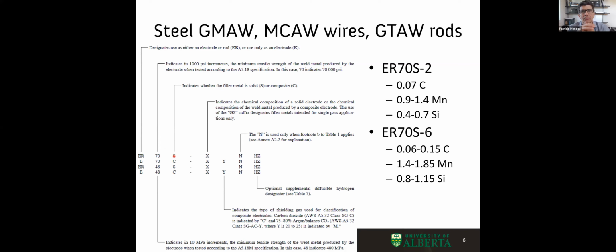Now, if we are doing metal core, because it's a metallic sheath, a tube with a powder inside, that is called a composite. And there are other types of wire that are not widely used commercially now. And I said not widely, maybe not at all, in which they would have stranded the wires. We have some samples of that in our lab, right? In which they thread 2 or 3 wires. So all those are called composite wires. Today, composite means pretty much only one thing, means metal core.